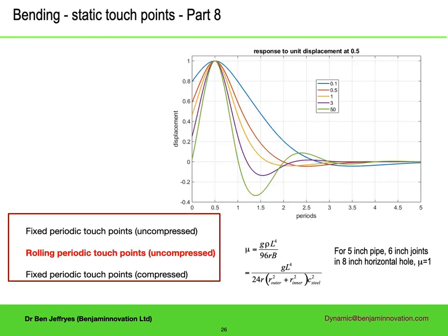For pipe or collars lying on the side of the hole, where the constraints are the joints or stabilizers, perhaps surprisingly, the propagation is greater in the vertical direction, where for small forces the joints are fixed to the low side of the hole, compared to the lateral direction, where the pipe can roll. The diagram shows how a unit deflection in one span propagates for different parameters.